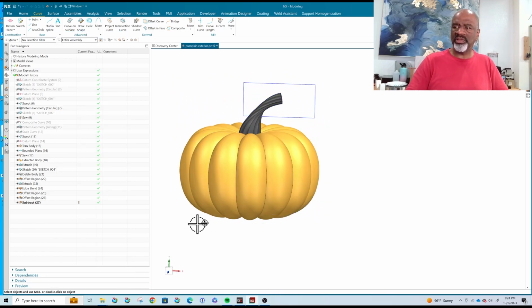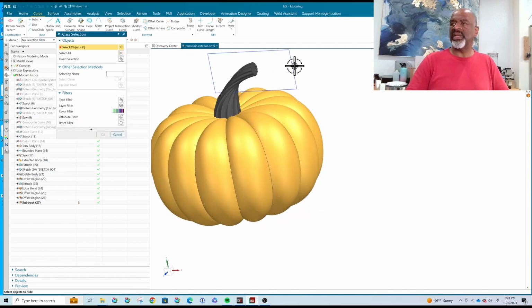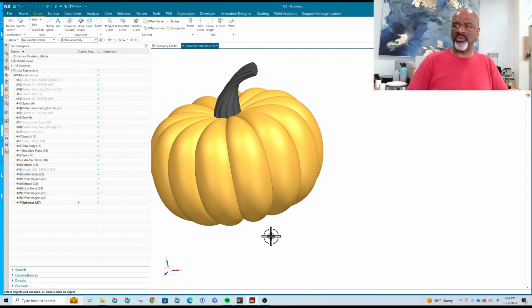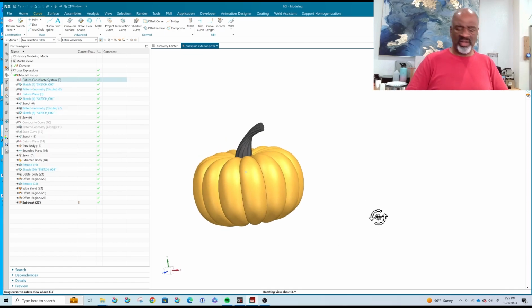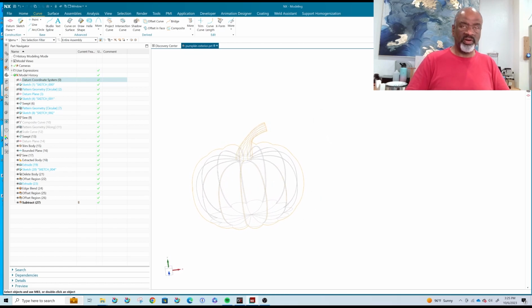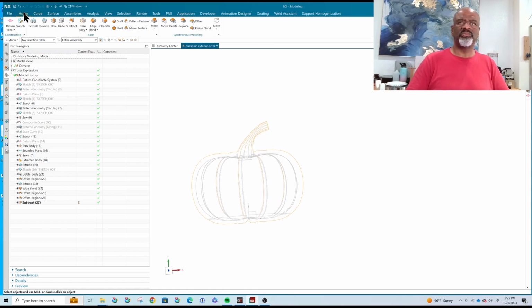Okay, so those are really powerful techniques that I wouldn't want to be without. And now I can go ahead and make the openings for the windows and the doors. And the windows and the doors can be drawn on the main coordinate system. So show the datum planes. Right here on the XY plane, we can make what we need.